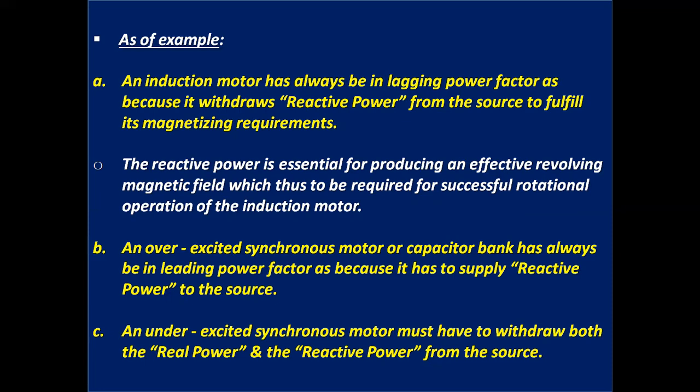An overexcited synchronous motor or capacitor bank always has a leading power factor because it has to supply reactive power to the source. An underexcited synchronous motor must withdraw both the real power and the reactive power from the source.